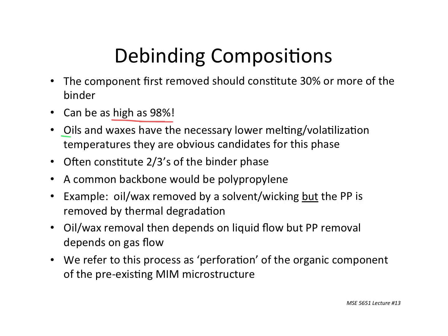And what they do is work with oils and waxes. All right, a very familiar sounding name for very familiar sounding components: beeswax, carnauba wax, paraffin wax. Things that were around 100 years ago or more are used here. All right, some very old style materials make for nice cheap components that can be removed relatively easily, and if you want to work at it, then you can easily precipitate your wax out of the heptane and recycle it and put it right back into the process. And so if you're willing to invest, you can have a zero waste process, at least in terms of the waxes that are involved in these systems.